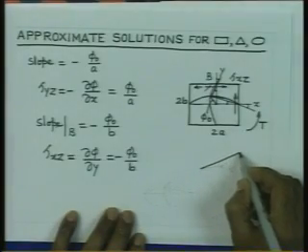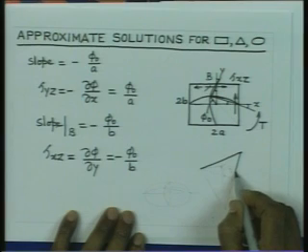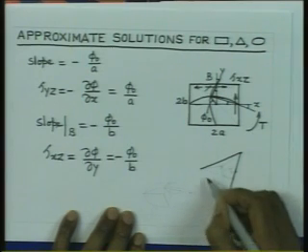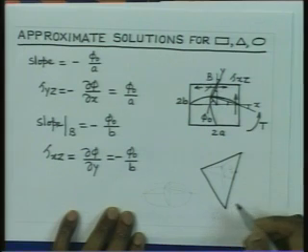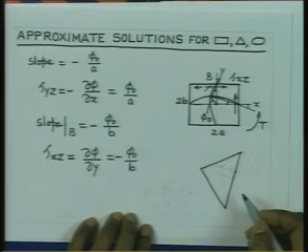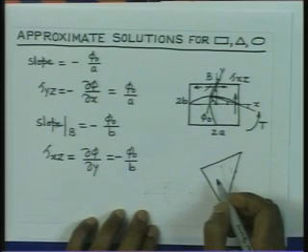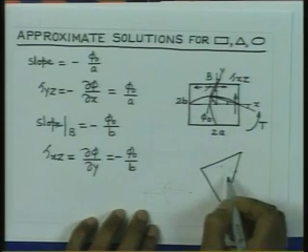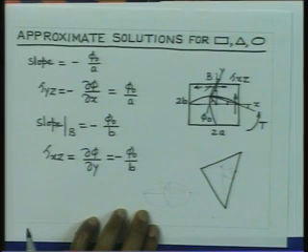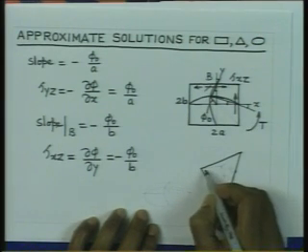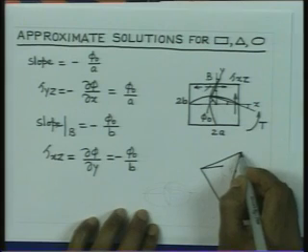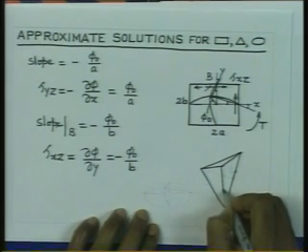I would like you to look into triangular cross section and elliptical cross section. Triangular cross section, if you consider, your membrane boundary is going to have the triangular shape as the shape of the bar cross section, and then we will find that the membrane surface is going to have a doubly curved surface, and it can be approximated by a pyramid again for first approximation.